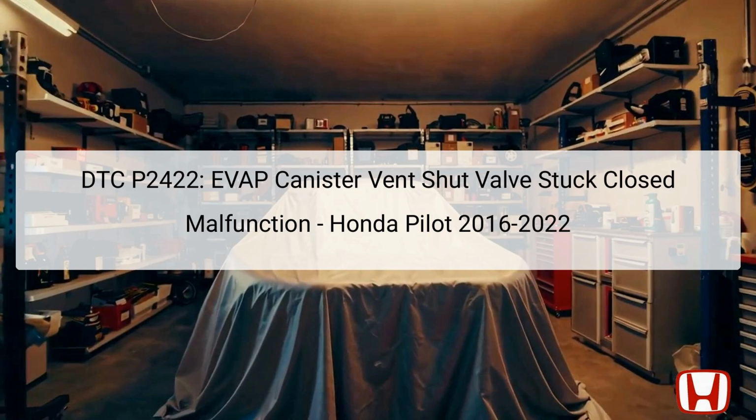The EVAP system utilizes various components, including the vent shut valve, FTP (fuel tank pressure) sensor, and associated hoses. In this scenario, the vent valve's closure can potentially lead to increased pressure within the fuel tank and can cause the vehicle's emission system to operate inefficiently.